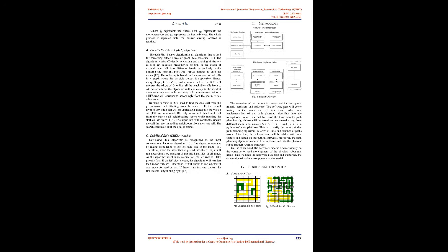A* algorithm. The A* algorithm is known as the best path planning algorithm, where it can be applied on any topological configuration space 5. The algorithm is a combination of both exhaustive search and greedy search 6. Exhaustive search guarantees an optimal path but requires long computational time. Greedy search excludes the optimal path by obtaining the overall search with less computational time 7. Both exhaustive search and greedy search are represented as the movement cost and heuristic cost of the distance.